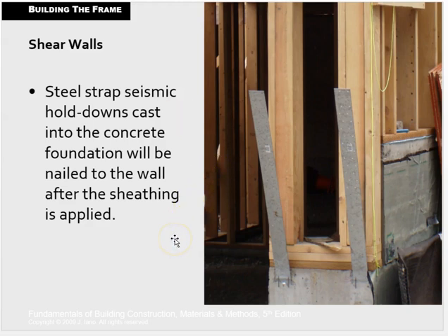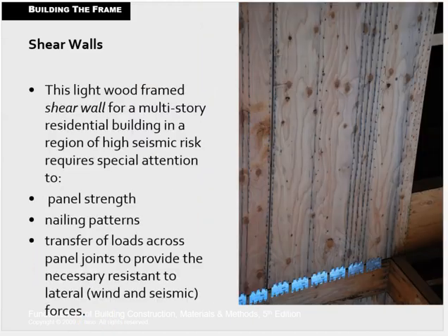But if you go down into Florida, for instance, and I've spoken to builders who have built there, it just adds tens of thousands of dollars to a project. These straps run from the concrete foundation all the way up to the rafters, and everything is just kind of held in by these members, but very, very expensive and very serious. Obviously, having roofs ripped off of buildings is very dangerous. So anywhere near hurricanes or earthquake activity, it's a much bigger deal. Here in Philadelphia, where the weather's pretty mild, less so.